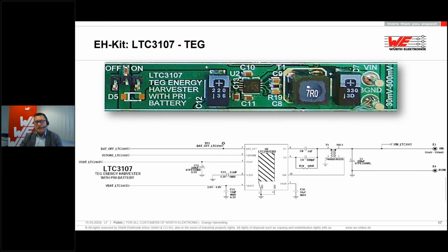And the IC is that clever. As soon as you apply this rising voltage to it, the first thing it will start to do, before it puts out output voltage or stabilizes anything, is swing this pin, the switch node. It is coupled to the transformer on the primary side. Then it starts to switch on and switch off, and by switching on and off, it generates from the DC voltage a flux in this coil, and then you have the 1 to 100 transformation.